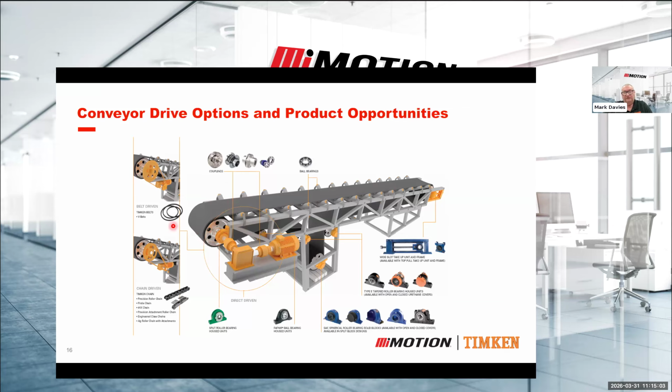And you'll notice that there's a number of what we call pulley drums. So the pulley is where the belt changes direction. There's a number of pulleys on here, both the tail and the head. You've got bend pulleys where it's literally a 90-degree change of direction. And then you have a take-up pulley here, which is a gravity take-up.